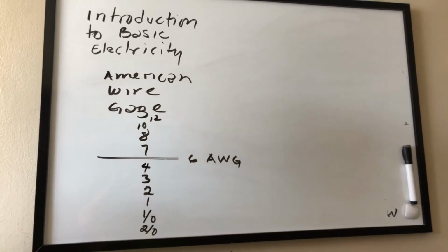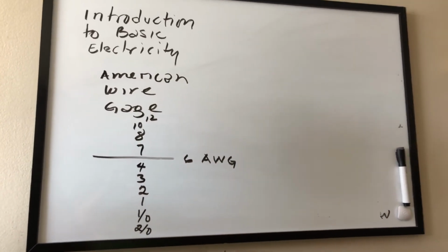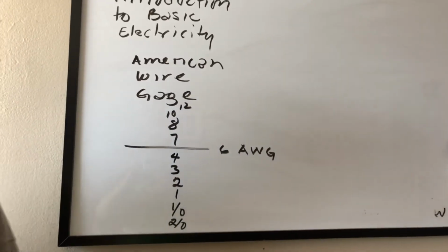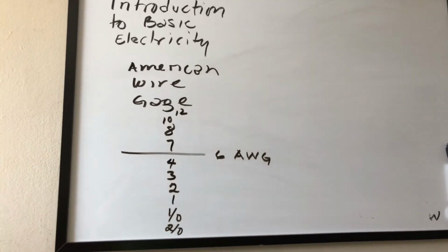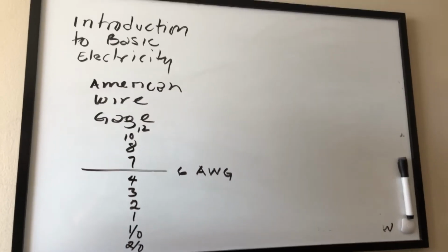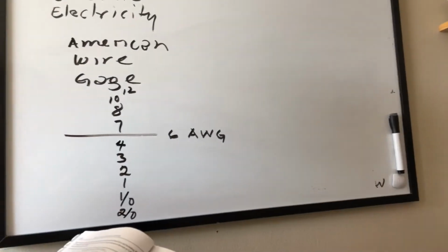The smaller the gauge number, the bigger the diameter, and the more amperage the electrical conductor is able to deal with. Okay. So where do we find the proper size depending on the electrical circuit? We need to use the NEC, Table 310.15(B)(16), and Table 310.15(B)(20).